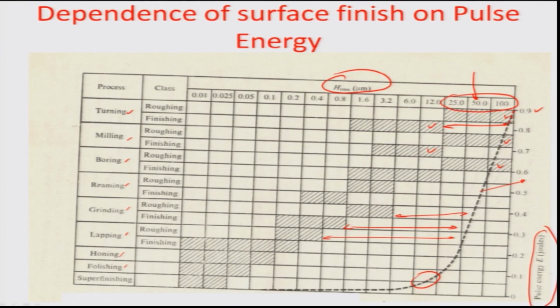So, this is not really a material removal operation, but more like a surface finish operation. Okay. Typically that low pulse energy of this grade, about 0 to 0.1, is only used in very specific cases, particularly in micro machining, etc., using electro discharge machining. Okay. So, that is how we can correlate the conventional processes and their outputs in terms of roughnesses with respect to what the spark machining does.